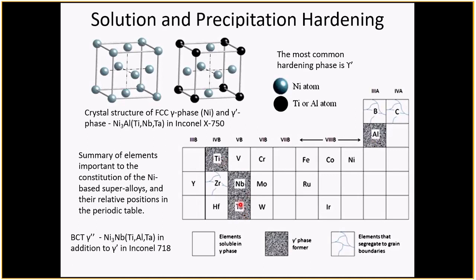Also, this shows typical constituents in nickel alloys, but also that boron and carbon will segregate to grain boundaries. Now, carbon and maybe not so much boron. Boron actually is an addition to nickel alloys to make them more formable. I think it has to do with boron segregating to grain boundaries, and grain boundary sliding is more feasible with this boron phase on the boundary at high temperatures, I think.